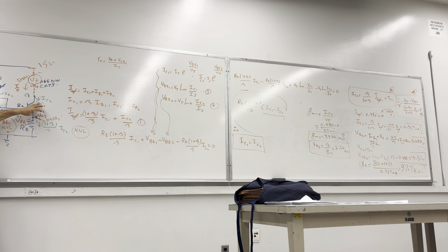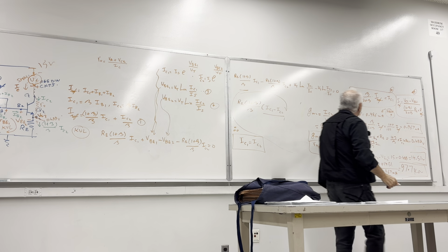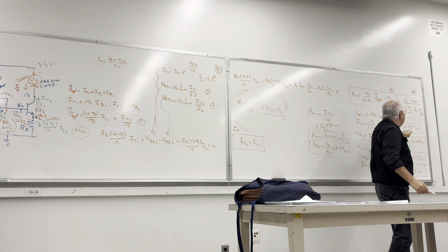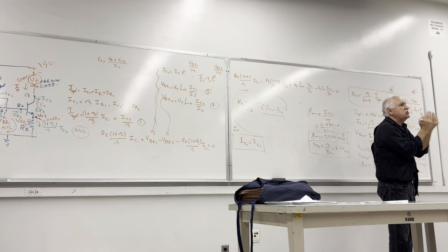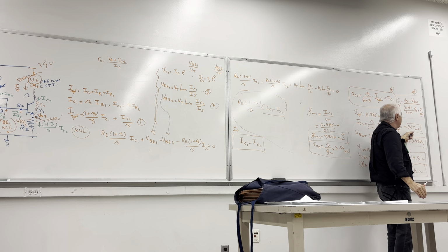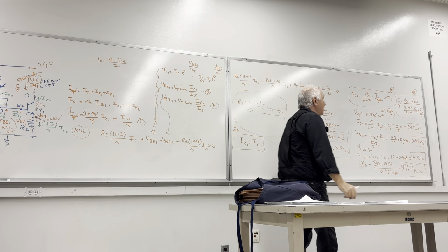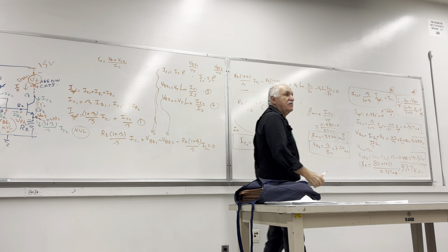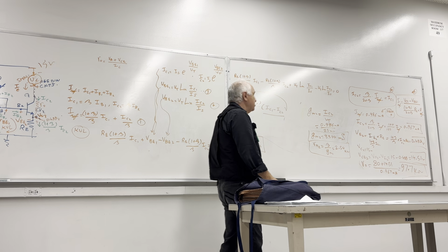That will tell us, indeed, what will be the dynamic resistance of this current source. Otherwise, we know how much is the current. The current is IC2, here, 0.96 milliamp, but it's going to change a little bit. There's something parallel with it. The resistance parallel with this one. So we want to know what is that resistance. In the case of a differential amplifier, that matters. You need to know the size of that resistance.